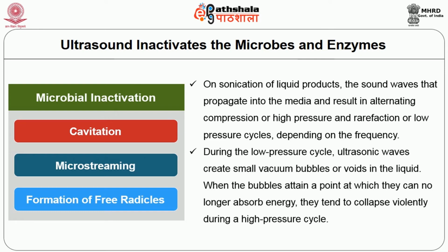During the low pressure cycle, ultrasonic waves create small vacuum bubbles or voids in the liquid. When the bubbles attain a point at which they can no longer absorb energy, they tend to collapse violently during a high pressure cycle. This phenomenon is termed as cavitation.